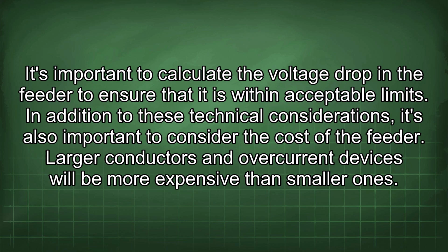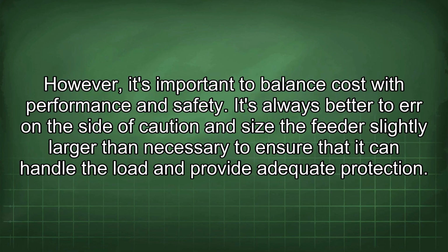In addition to these technical considerations, it's also important to consider the cost of the feeder. Larger conductors and overcurrent devices will be more expensive than smaller ones. However, it's important to balance cost with performance and safety. It's always better to err on the side of caution and size the feeder slightly larger than necessary to ensure that it can handle the load and provide adequate protection.